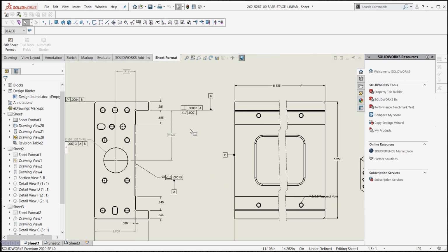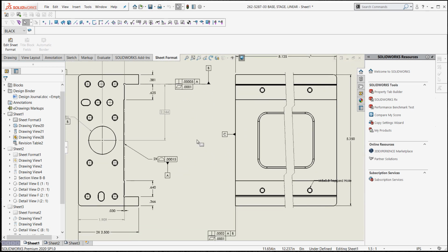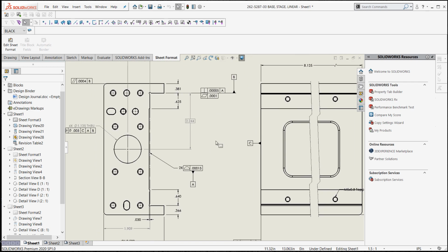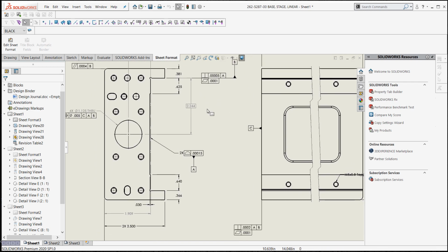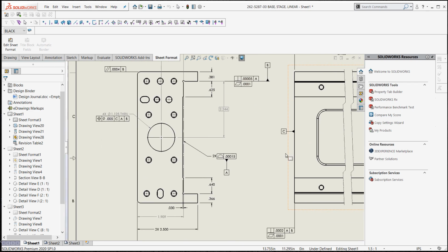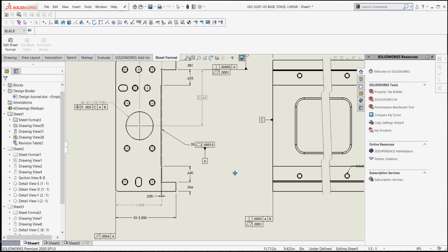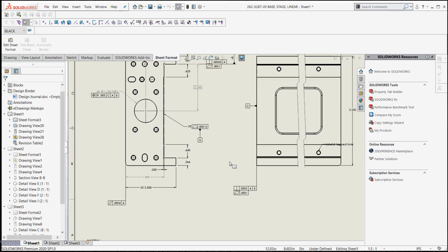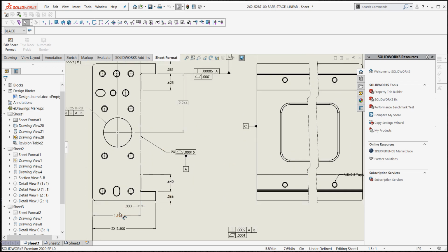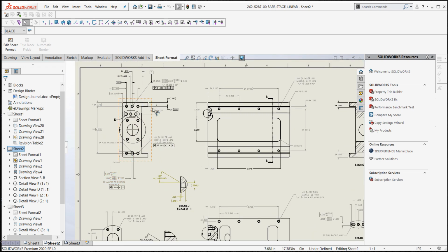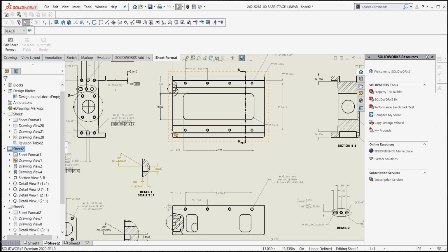And if you look, this drawing has 4 microns, 1¼ microns of tolerancing for surface profiling, flatness, and perpendicularity. Pretty tight tolerancing, let alone some tolerancing for the true positioning of the model. So what I really want to do is duplicate this information that's on this multi-sheet drawing for all the